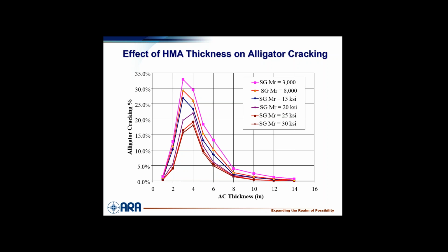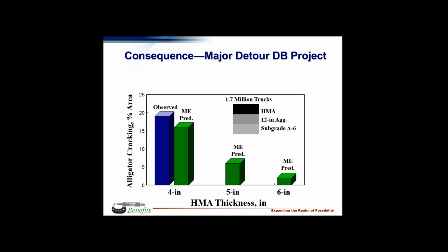If you go thicker than that, it gets lower. The strain goes down, and consequently the fatigue cracking. And your subgrade can be from extremely soft to very stiff. And well, there is a difference here, and many of these soils were quite soft. So basically they had about 20% in one year, 20% of the lanes failed, which was a massive amount.